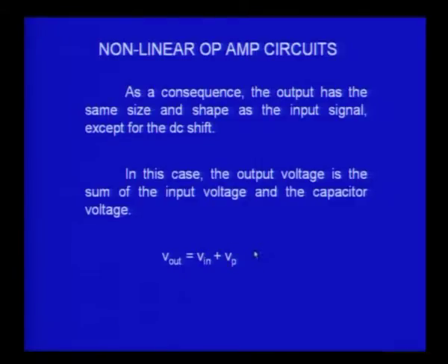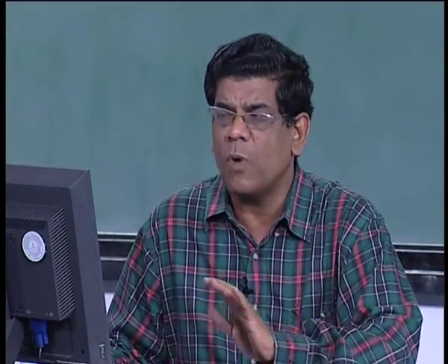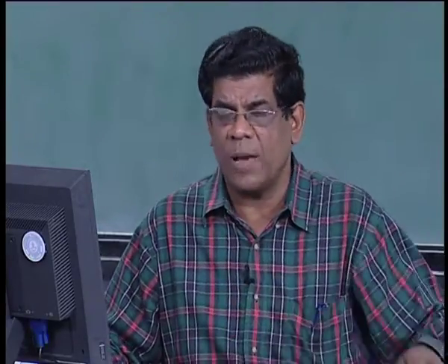When I add it with this, so when this becomes plus Vp, the total becomes 2 Vp, when this becomes 0, the output is Vp, when it becomes minus Vp, the output is 0. So, there is nothing which goes below 0, even though the signal goes below 0, because you are adding with a Vp, the output becomes only all positive starting from 0 up to a maximum of 2 Vp. So, that is the active positive clamper that we wanted to discuss. Now, I will try to show you the demo of the active positive clamper, and then we will go further.